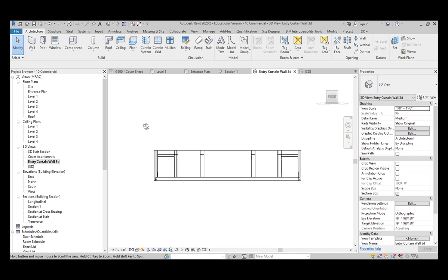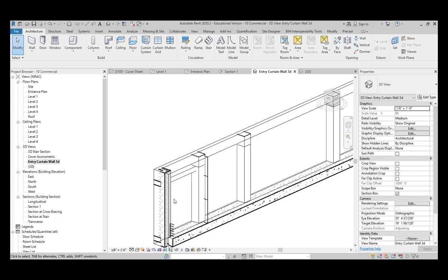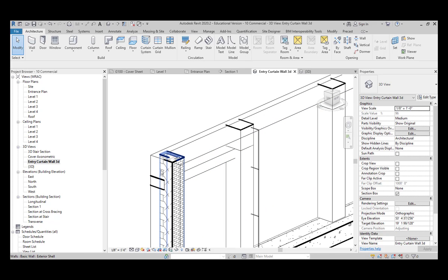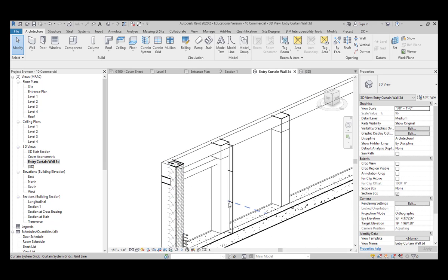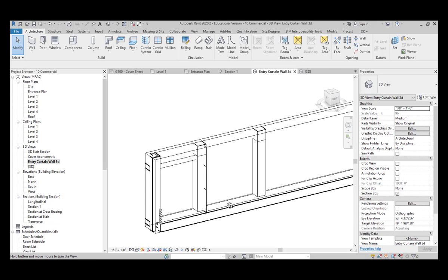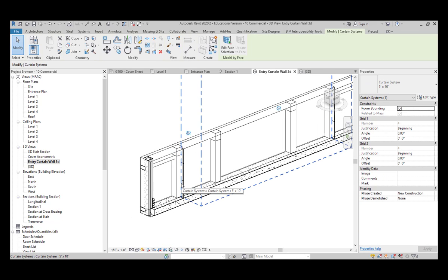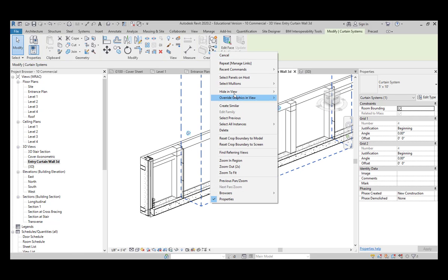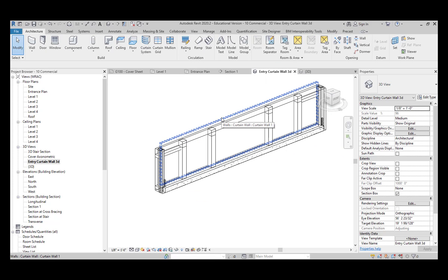This is a 3D view. I can rotate it a little bit, and we can see that that's the 3D view of this object. And we've got some of the walls cut open, so we actually see the cut mark, and then some of it is visible, and we see the front of the brick here at the corners. There's one more thing we want to do to this, which is to hide this element. So you're going to grab it. That's that curtain system that goes up over the front of the building, and it's in our way right now. So what I'm going to do is I'm going to select it, right click, and I'm going to say hide in view element. Okay, and this is where we end on page 435.